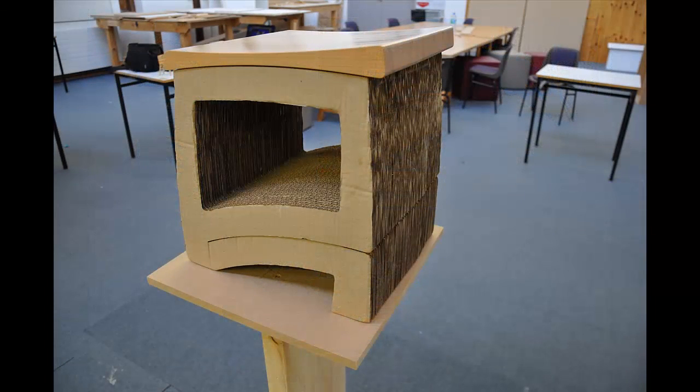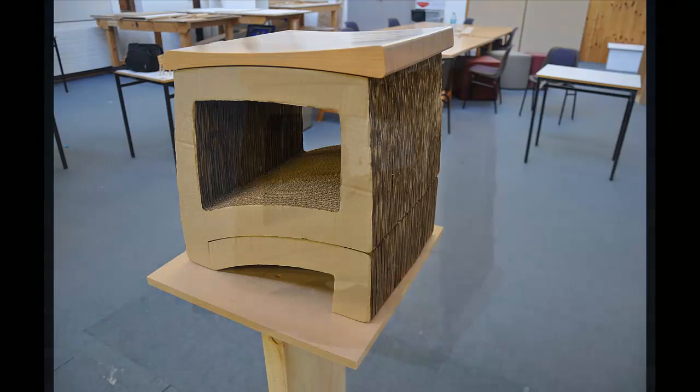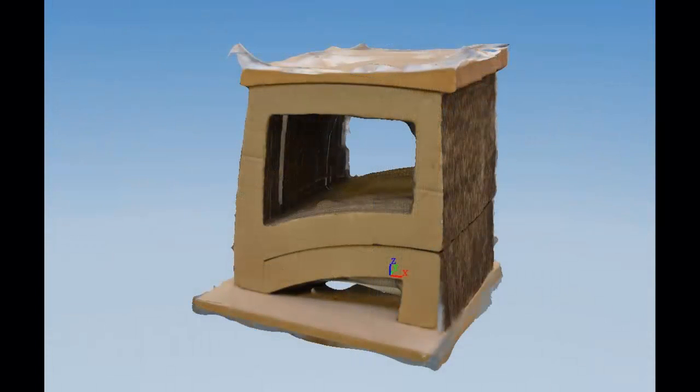The photographs shown show a stool with a lacquered seat. Note the way the light is reflecting on the surface of the seat. When the 3D model of the stool was produced on 123D Catch, the light changes between the multiple photographs caused distortions which can be seen in the next photo. To prevent this from occurring, reflective, transparent and shiny objects should be avoided. Alternatively, a different photography technique may be needed to eliminate the glare on the surface of the target object.